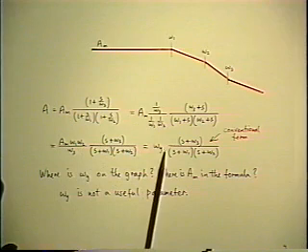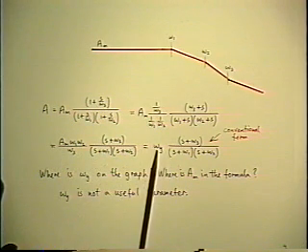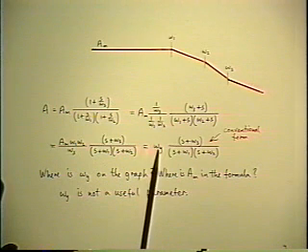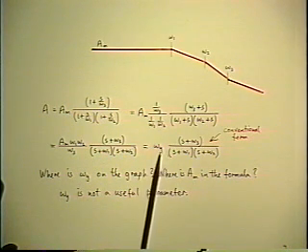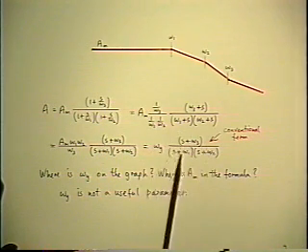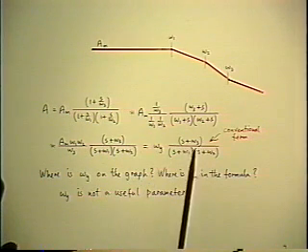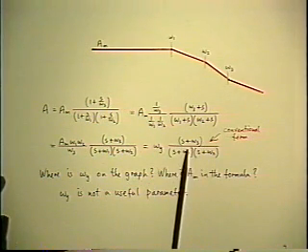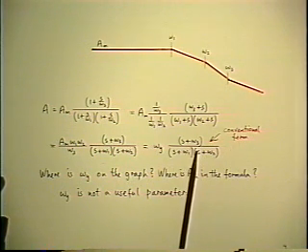That parameter, once again, is a frequency and not a gain. And you have to realize that even to get the right sort of symbol. The coefficient in front must be a frequency in order that the dimensions of the whole expression come out right. So this is also a correct result, and maybe even more conventional than before.